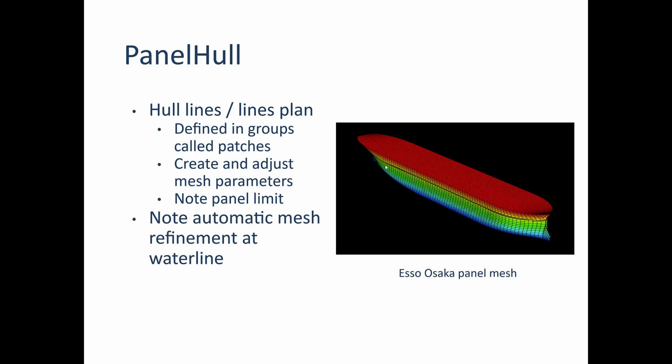Note that Shipmo3D will automatically refine the mesh at the water line of the vessel. That's really crucial for improving numerical accuracy and reducing noise in the calculations.